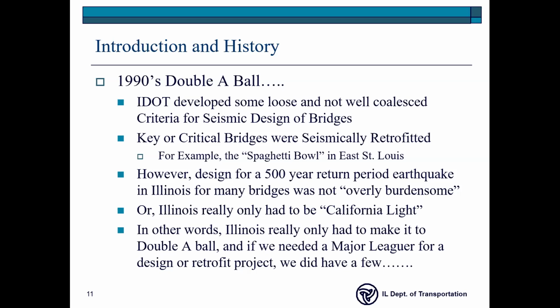But on the flip side, in Illinois, with a 500-year design return period, the seismic demand, or the accelerations we were required to design for, really weren't that high unless you were down near the very far southern tip of our state, near a town called Cairo, Illinois. Okay, so we had to learn seismic in Illinois in the 1990s, but we didn't have to learn it nearly as well as the folks in California had to know it.